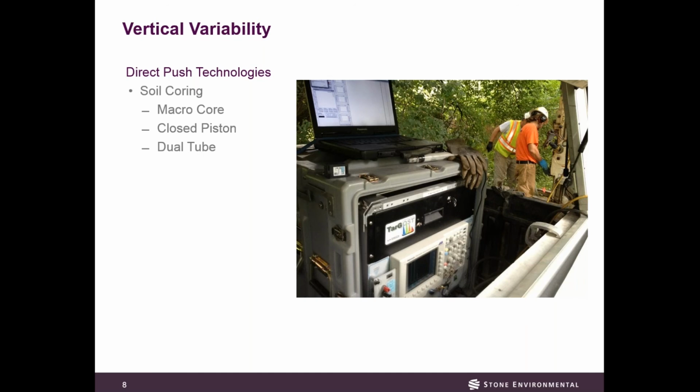And so you need to select, if you're doing the sampling with this, when it's 9/16 of an inch diameter, and you're trying to get from a very discrete interval, obviously you're not going to have enough volume to fill the jar. So you've got to select a tool that's appropriate for the volume you're trying to get, because you don't want to have to go down with another run to get more volume. That'd be very time consuming.